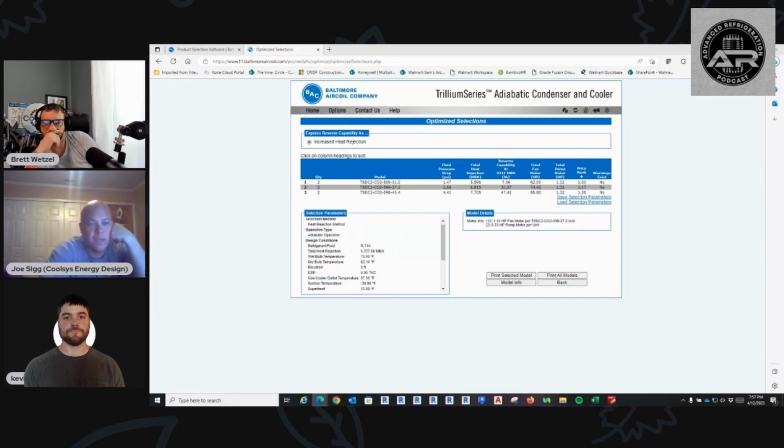Yeah. So that seems to be like an issue at almost every single CO2 store up here. We have tons of gas cooler for the summer, or a decent amount of gas cooler for the summer, but then winter hits and you're oversized. Yeah. And even when you're running static, no fans, you're still oversized? Oh yeah, big time. Really? The wind, and then it's just the load at night.